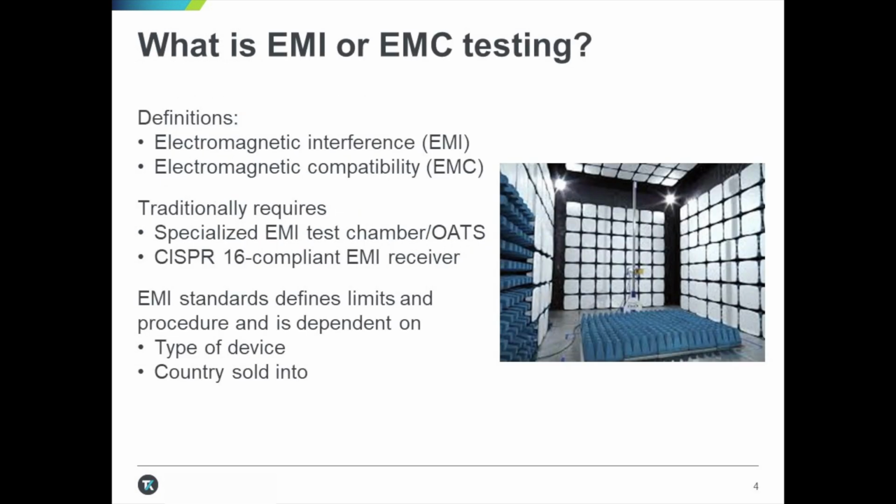If you don't know, EMI, or electromagnetic interference, is the disruption of operation of an electronic device when in the vicinity of electromagnetic energy of an external electrical source, either man-made or naturally occurring. Sometimes called radio frequency interference, EMI can cause devices to not operate correctly or how they were intended to. Sources of EMI are usually man-made, coming from other electrical devices such as switch-mode power supplies, internal circuitry, personal computers, and cathode ray tubes for older products, just to name a few. But it can also be naturally occurring, coming from things such as electrical storms, solar radiation, or cosmic noises.